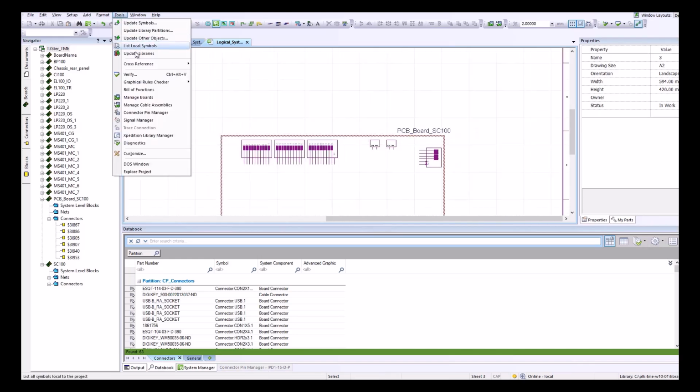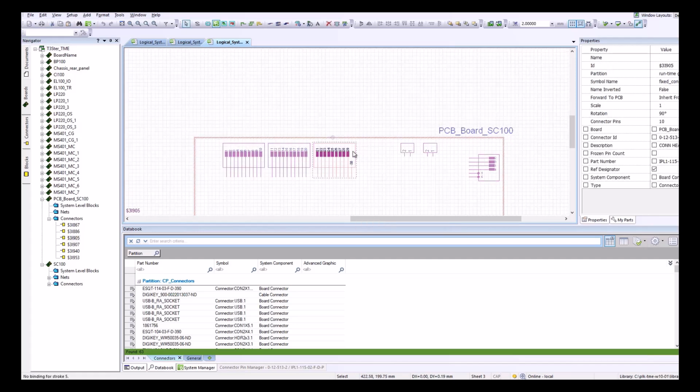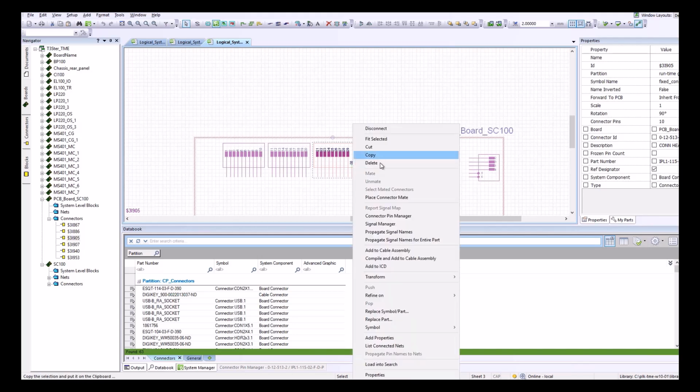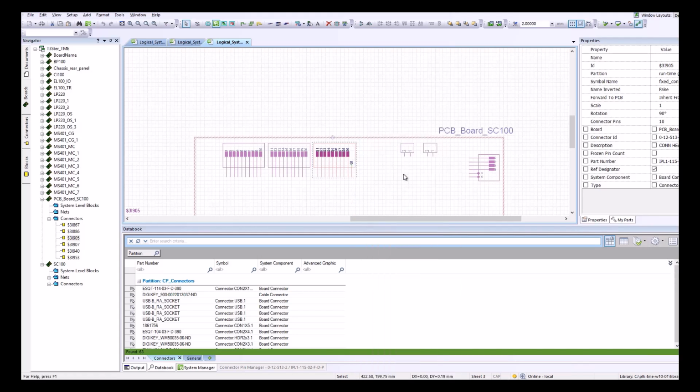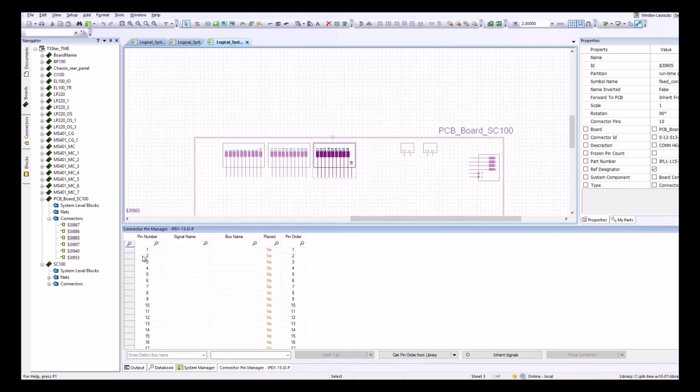connectors. So in the example, one of the boards in the design has a board connector, which is mated with a cable connector. And you may see the board connector here is located within the rectangular shape, and that shape represents a physical PCB in the system design. So a list of approved mated connectors for this board connector was specified in EDM library.